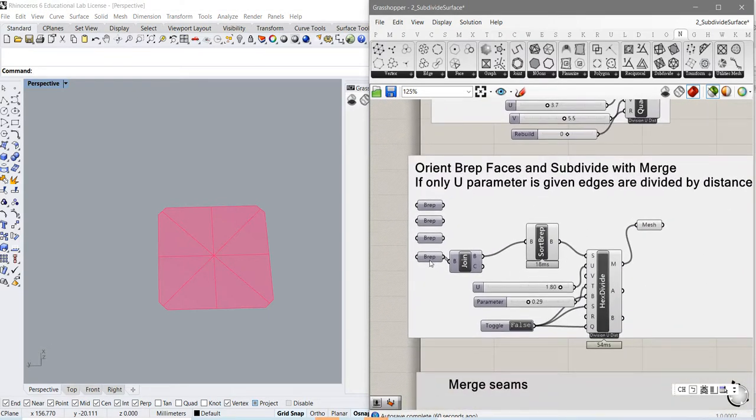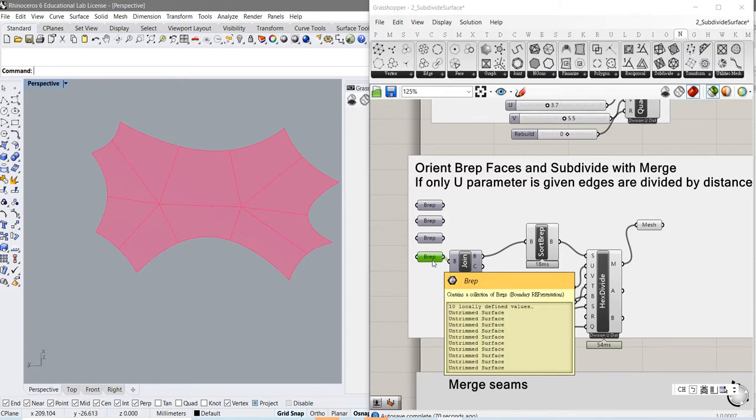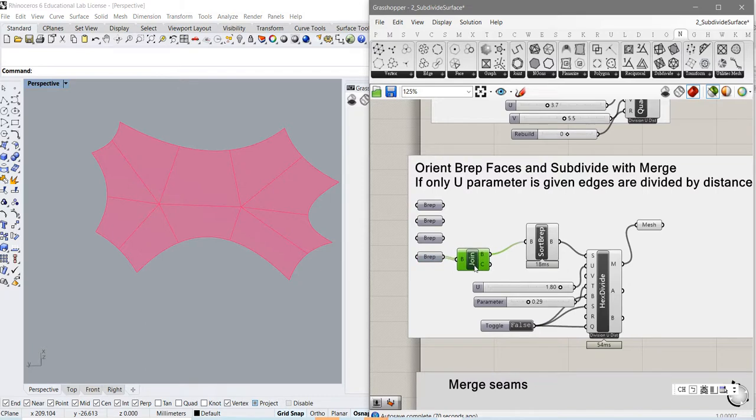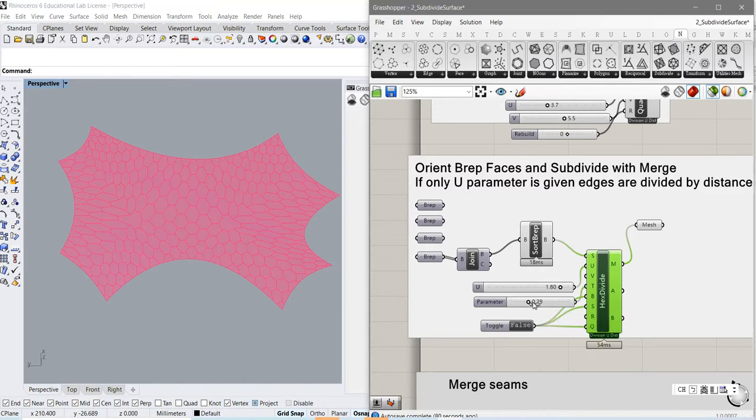Okay, for example, like this one. Now we have surfaces with different shapes, different sizes, and different dimensions. There are 10 surfaces. You join them, then you sort it, and then you apply this hexagonal division. Then you get something like this. Again, because it is a hexagon, we can change the parameter, so you can get an indented hexagon or a convex hexagon. This is a concave hexagon, a convex hexagon, or rectangles if you have 0.5 for the parameter.